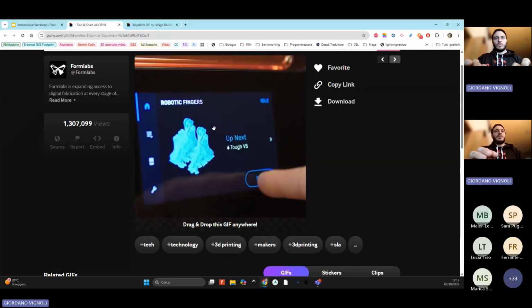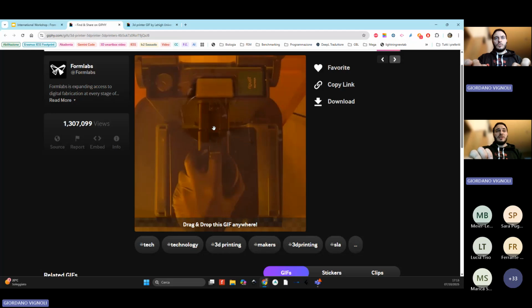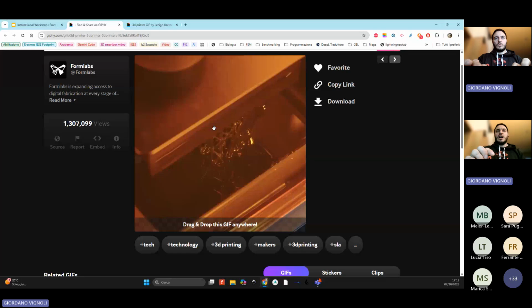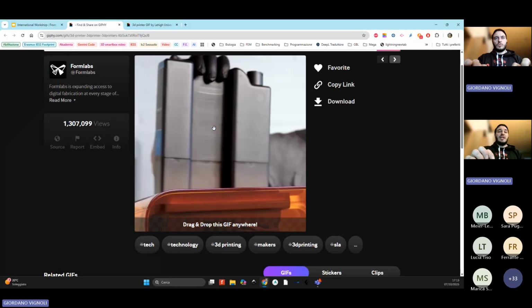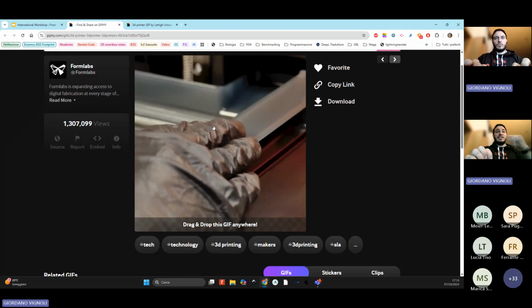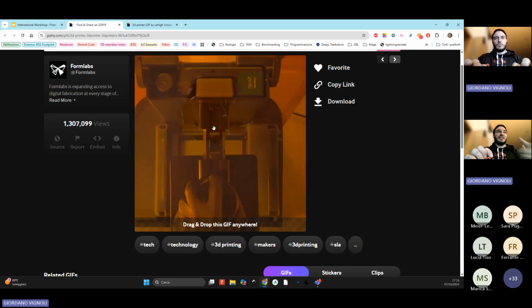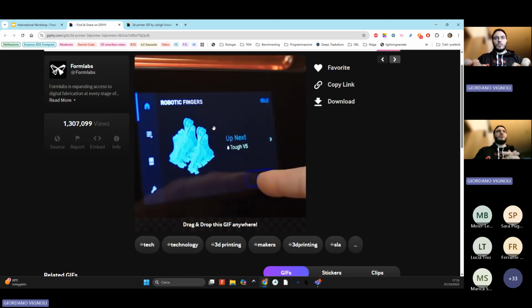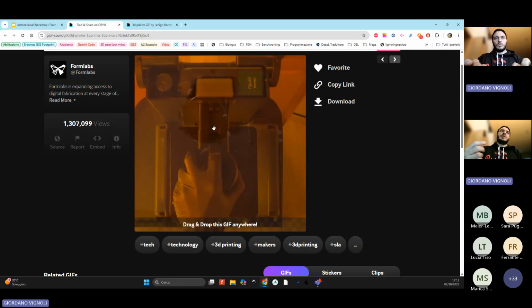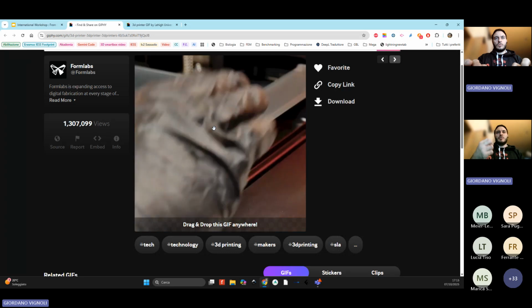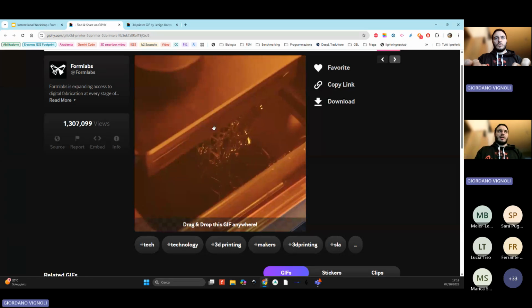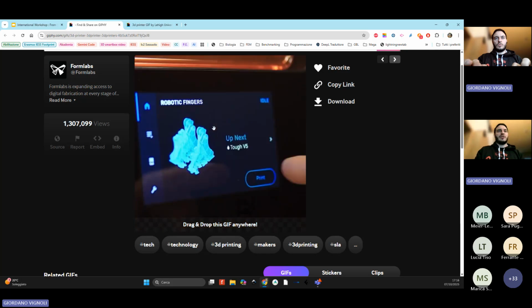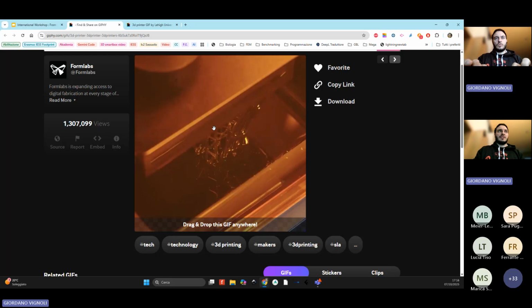With resin we speak about layers of 0.05 millimeters. So the quality is higher, the precision is higher. You will have an object in which you will notice the layers with more difficulty, not like in fused deposition modeling, which has higher layers.